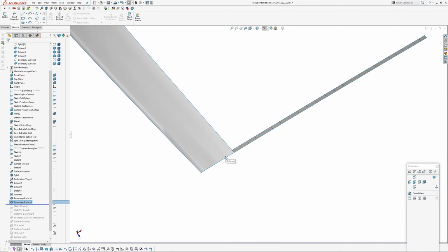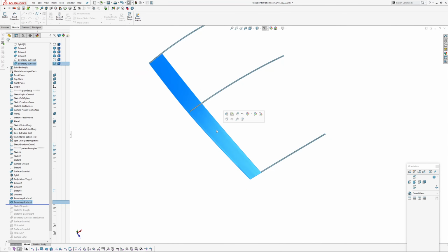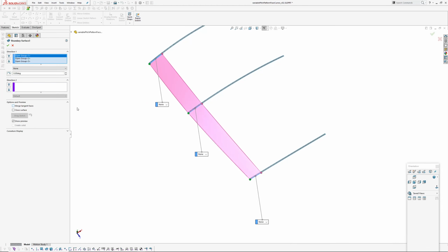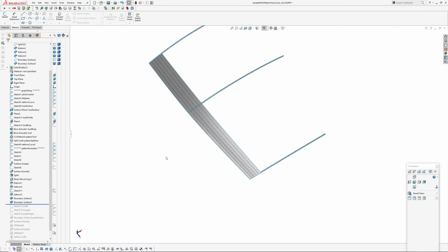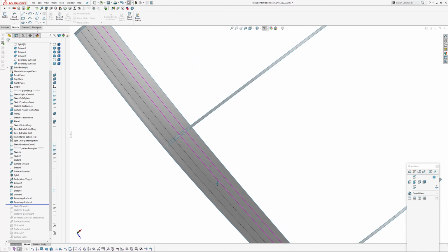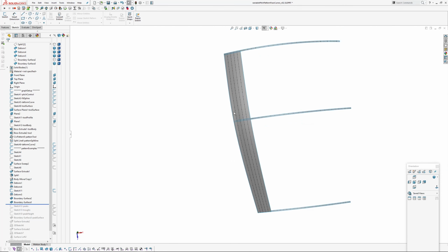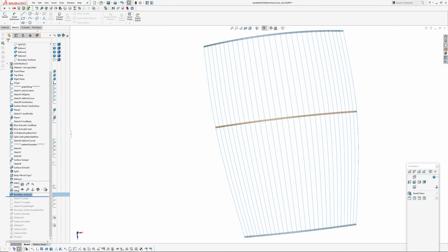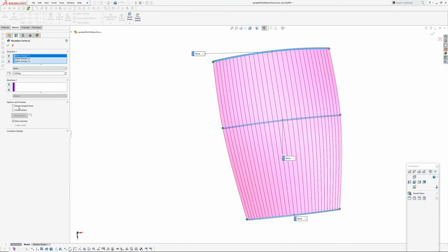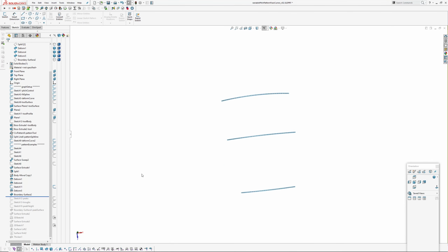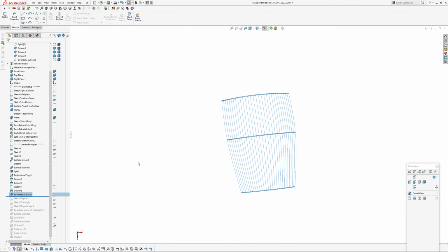And then selection manager again, 1, 2, 3, 4, 5. Now if I went OK there, we'd just come out with one surface. So what you want is to turn merge tangent faces off, and then you get the lines. So Solidworks is just extrapolating or tweening between these segments. If I go into this actual boundary surface, you can see I've got merge tangent faces off.